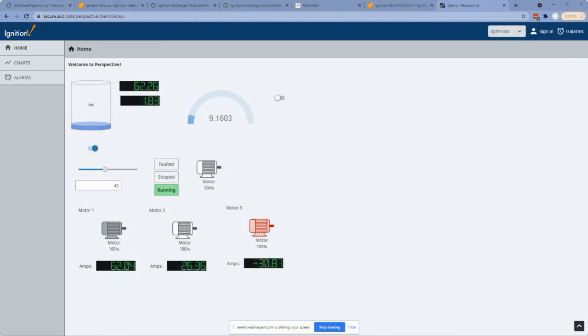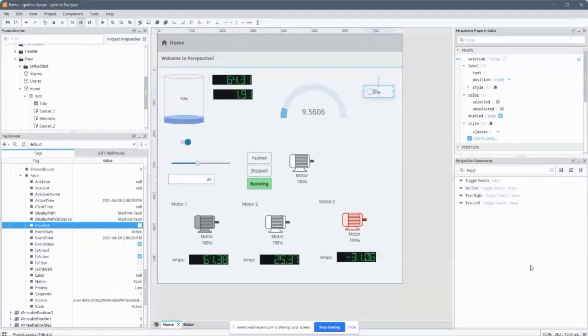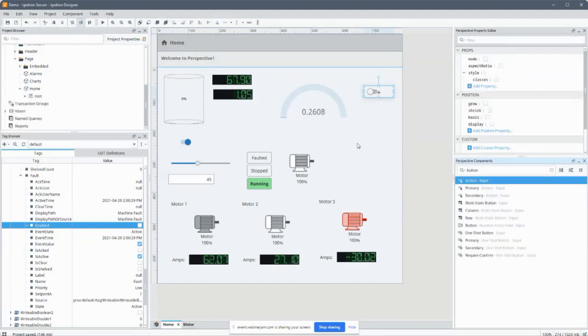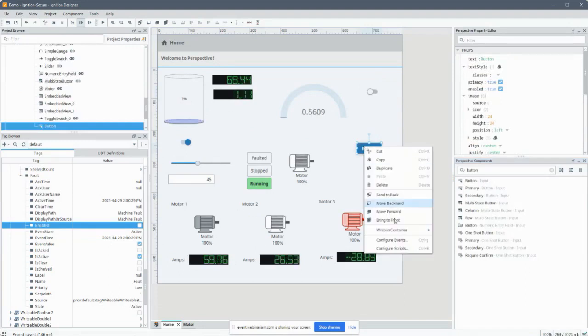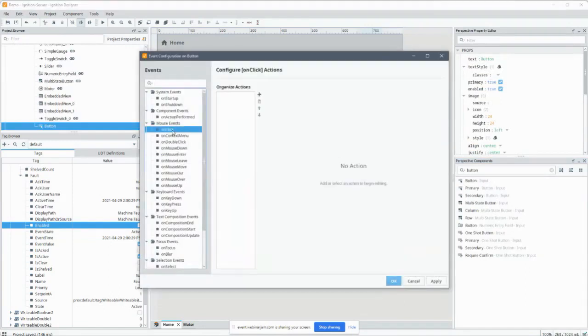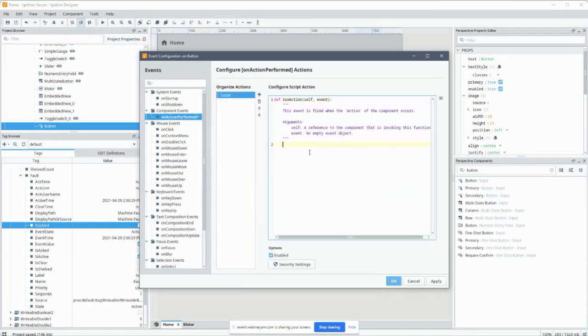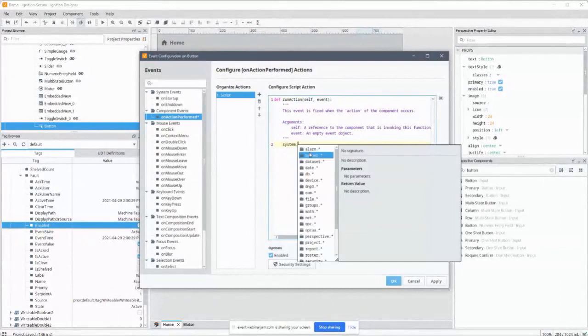And a good question from somebody else is, what is the background programming language? I totally glossed over that in the demo. There definitely is scripting built into Ignition, very well integrated in the system. We use Python, so you can go onto buttons and various things like that, or you can configure a script. In Ignition, we have over 300 or 400 scripting functions to do things really easily and quickly, as you can see with this list, from database functions to tag functions and so on.